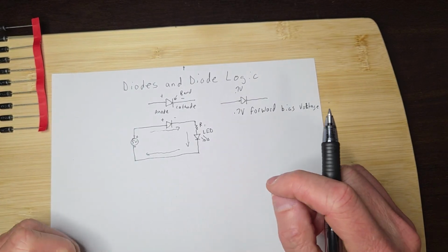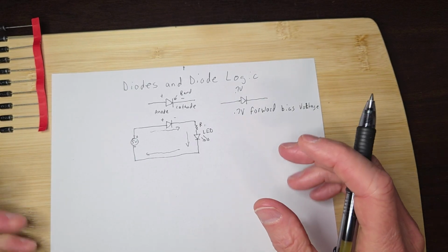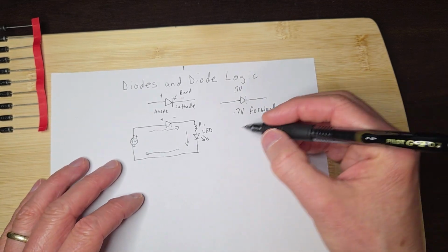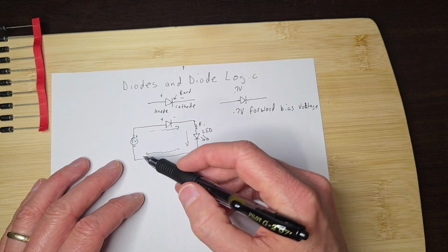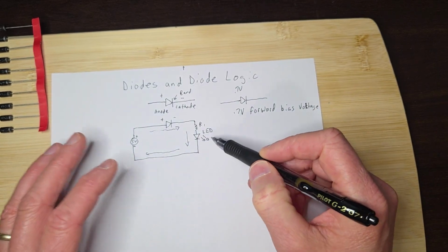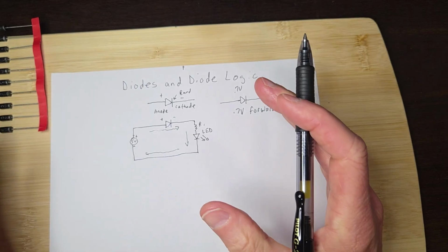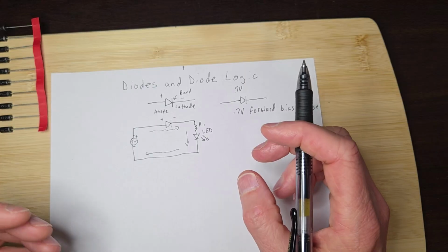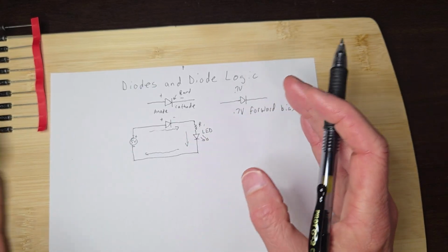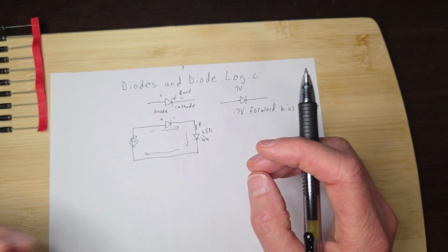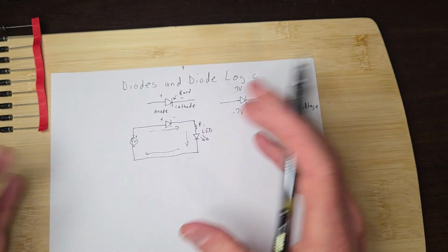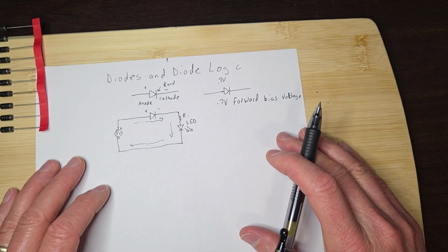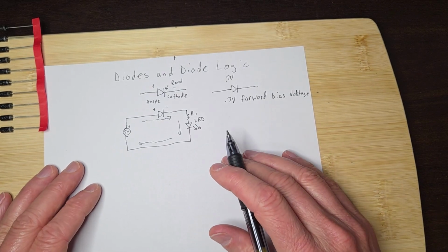That's like when you have a charger for your phone: you plug it in the wall, and it's taking an AC input and turning it into whatever DC we want. We can take an AC input of 115 volts and, with the use of transformers, capacitors and diodes, convert it over to a solid state DC value like 5 volts or whatever we want. So that's a pretty interesting use for diodes, but diodes can also be used as logic gates.